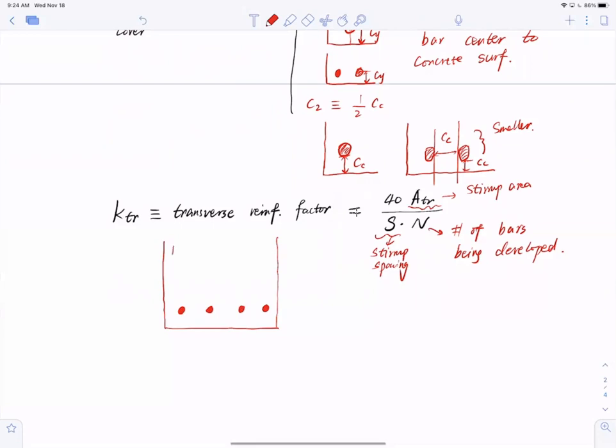So I'm gonna draw a stirrup this way. It's gonna go to this bar here, going up, and then go around it like that. Okay, and I say this is not enough. I need another stirrup going this way. My drawing is still horrible, but you get the gist. So now I have 4 legs going across it.